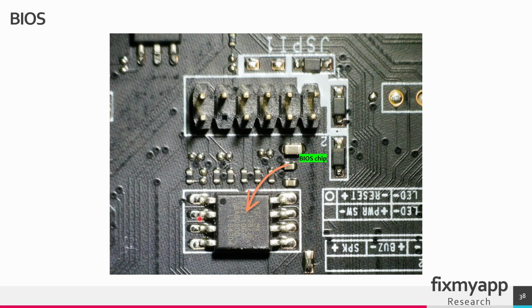working BIOS. Updating the BIOS improperly can result in a corrupted BIOS version, causing the system to be unstable or not boot at all. This is why many motherboards include a dual BIOS system that offers a backup BIOS in case an update goes wrong.